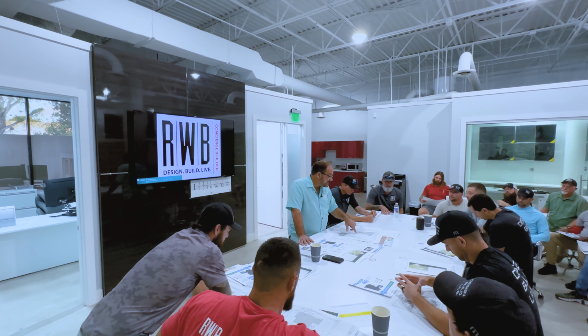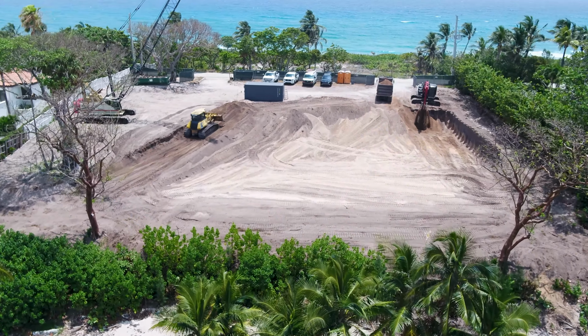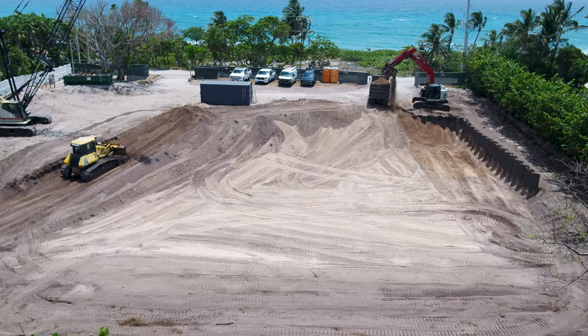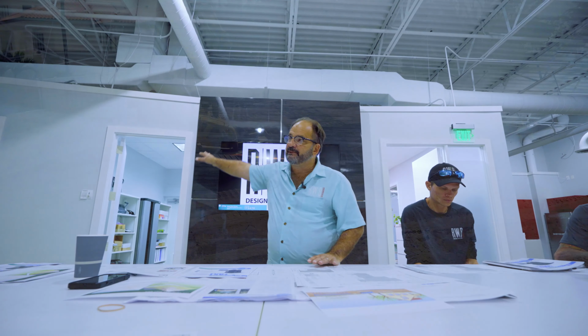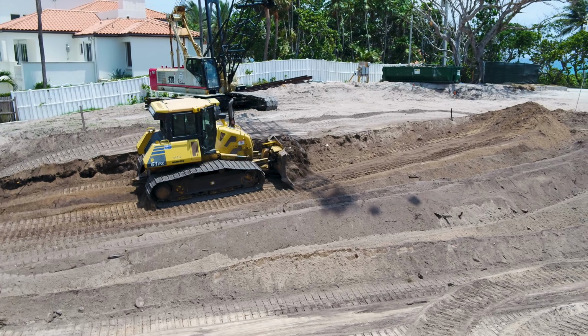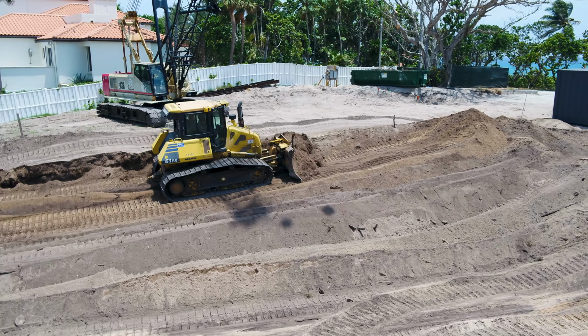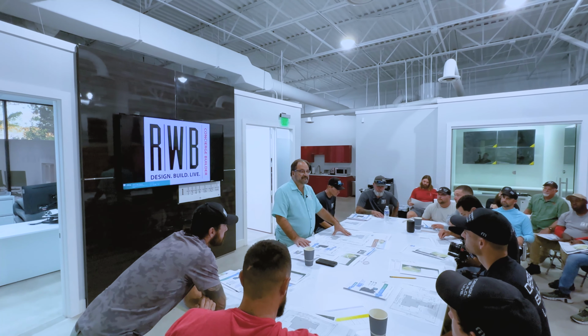When we build this house, we put sheet piles around the house. Everybody know what a sheet pile is? Okay? The reason we do that is when I put this basement in, I have to cut this down 12 feet. If I cut this grade down 12 feet, it's going to be all the way to the street. I'm not going to have enough room to pitch it to the neighbor's properties. So I have to put sheet piles in so we can lower the grade within the sheet piles. Okay? All this has to be thought out.